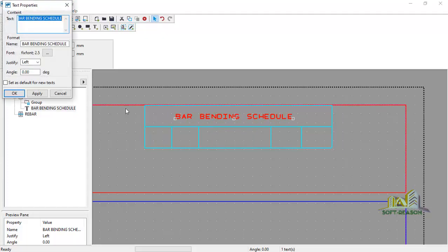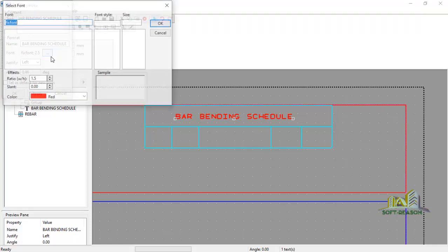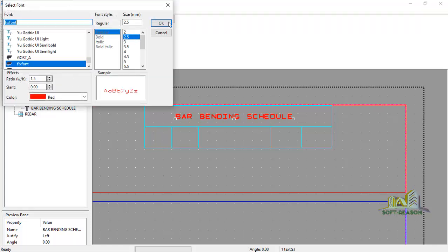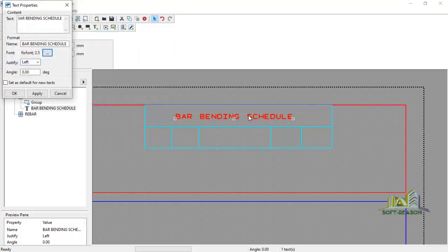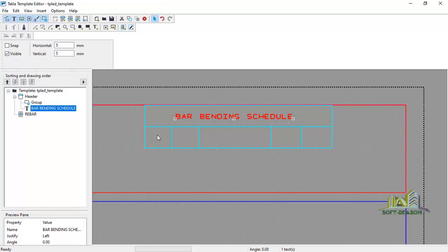If you click on this text, you can see some other items here like the font and the text height. If you click this point, you can set the text height. All right, so click on OK, including the color of the text. Okay, so I will apply and click on OK. So the next thing, I'll be having text in all these partitions.